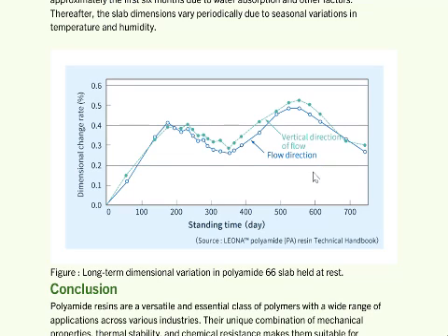Some practical considerations regarding polyamide also include processing conditions. It is essential to optimize processing conditions to achieve the desired properties and minimize defects such as warping, shrinking, or surface imperfections. As mentioned above, moisture sensitivity is one of the concerns in forming polyamide resin.